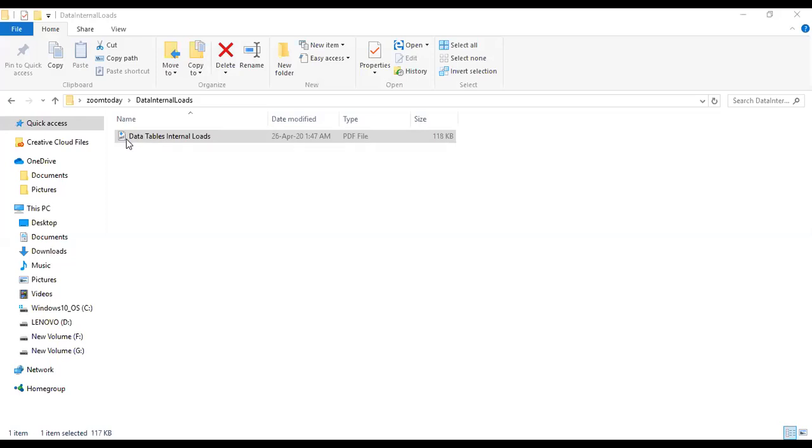So according to this table, here is the number of hours of operation: 10 hours, 16 hours, 10 hours, 16 hours, two different columns. For 10-hour operation, one shift; for 16-hour operation, two shifts. And this is the number of hours after lights are turned on, hours of operation. So by using this table, we can find out the CLF, cooling load factor. That means what is the effect of radiation transfer from these lights.